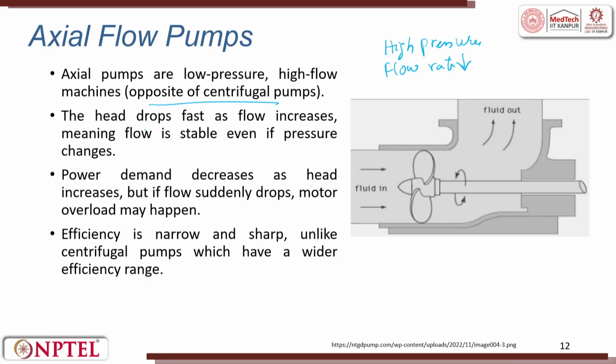The head drops fast as flow increases. Head is what? Pressure. The head drops fast as the flow increases, meaning the flow is steady even if the pressure changes. The power demand decreases as the head increases. Head is the pressure, head is the overhead, whatever you have. But if flow suddenly drops, the motor overload might happen.